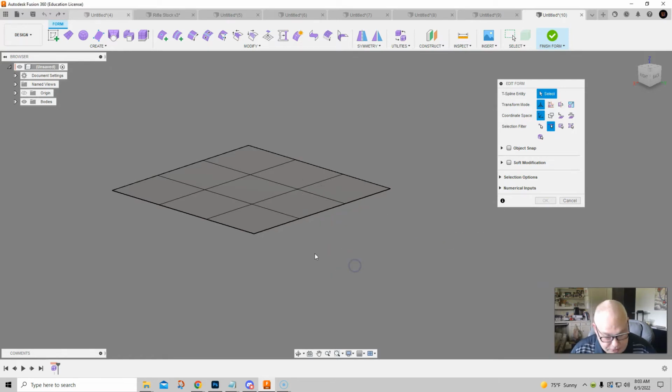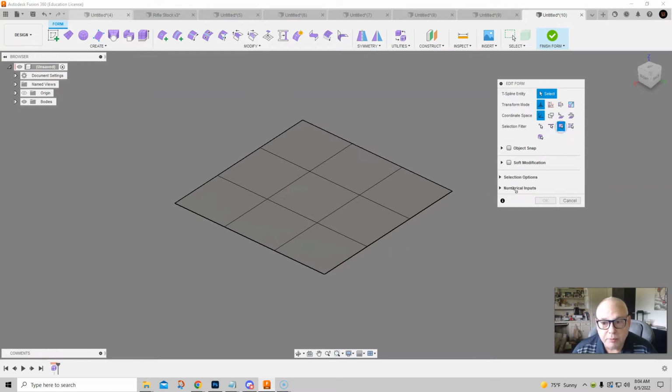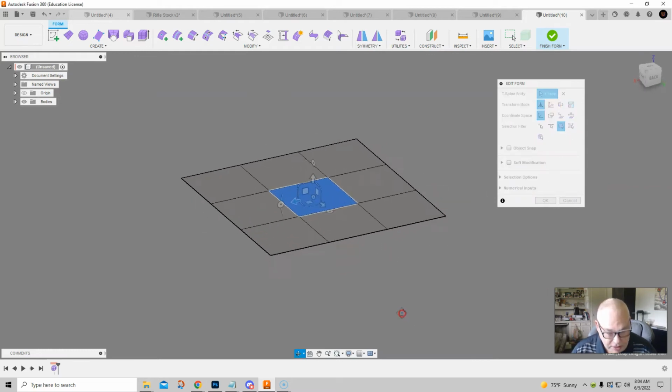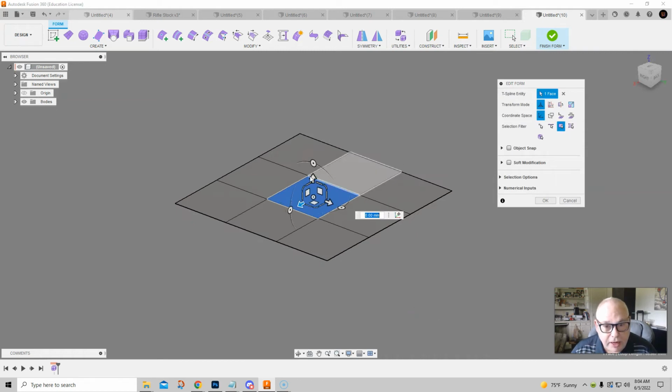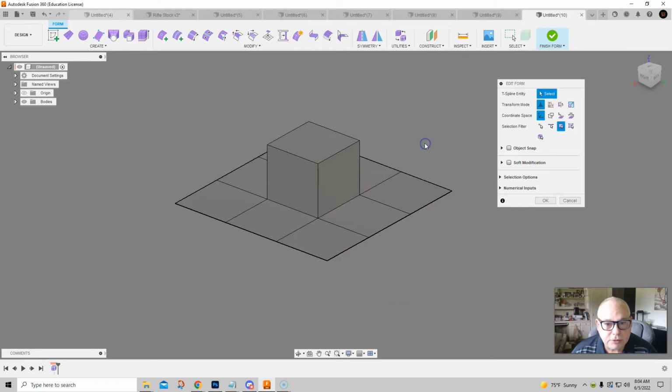All right. So what we're going to do is we're going to come in here, and I'm going to go to my polygon mode, or my face mode, and I'm going to hold an Alt key, and I'm going to pull straight up, and I'm going to want this to be more crisp. Okay, so I'm going to go Alt-1 to look at this. All right, there we go.